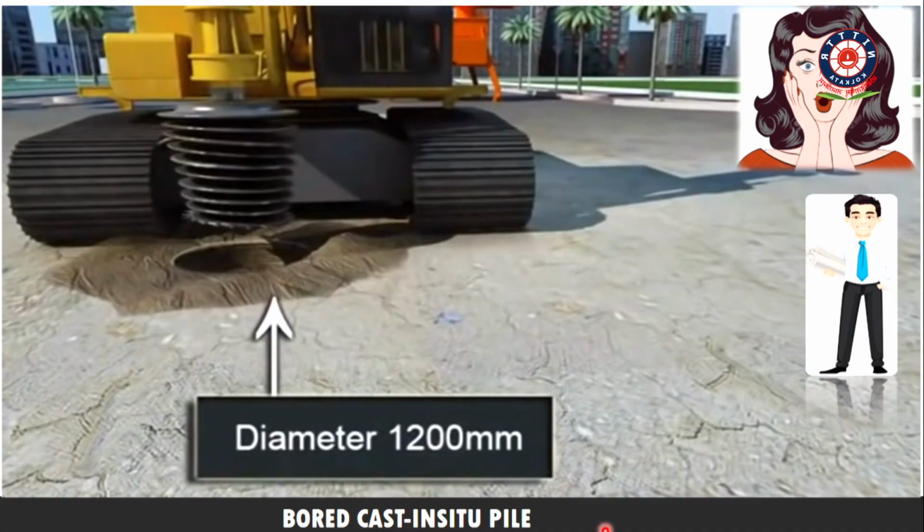Next method is bored cast in situ pile with the help of the rotary method. In the rotary method, first you identify the pile point, then you insert the casing at the required depth.